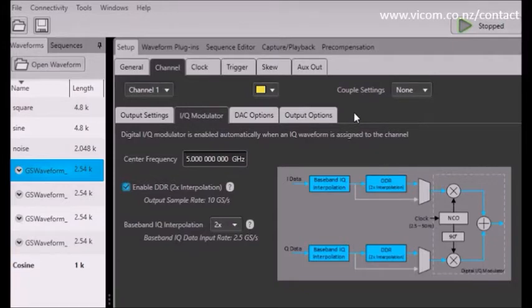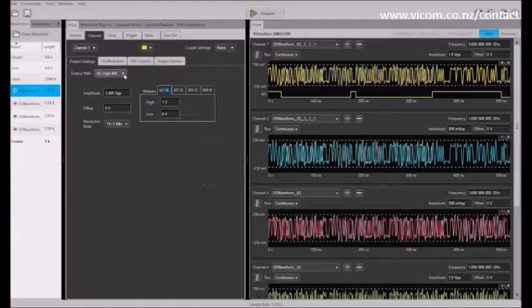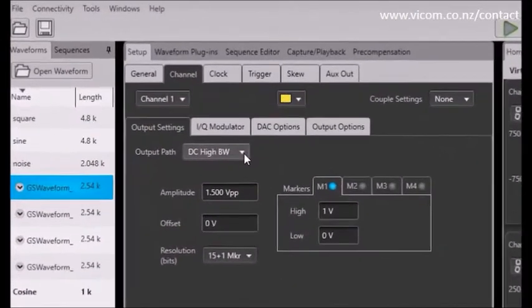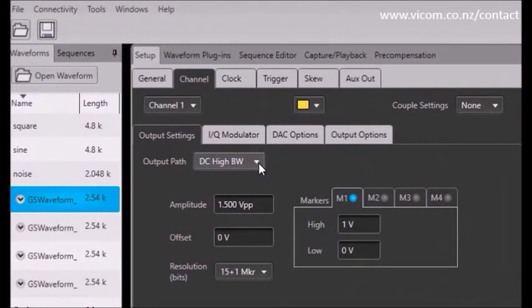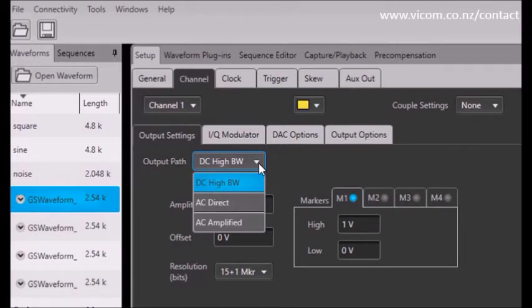This allows for baseband IQ waveforms to be internally modulated with a carrier frequency up to 5 GHz, removing the need for external mixers that can degrade the performance of your IQ signal generation and reduces the need for using 2 channels for the external IQ outputs. The AWG5200 series also has incorporated several DC output options as well as AC output capability, including amplification and offsets